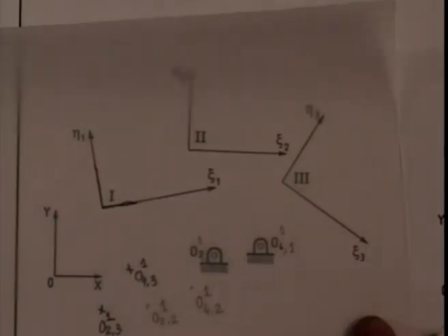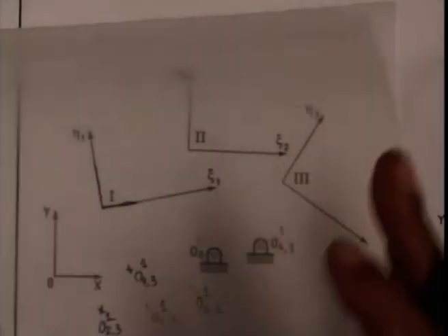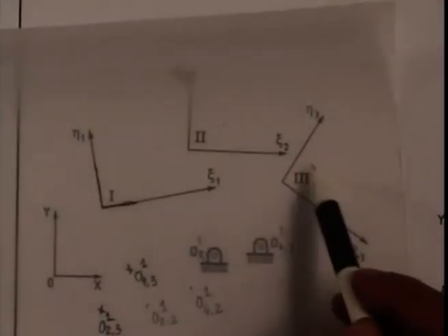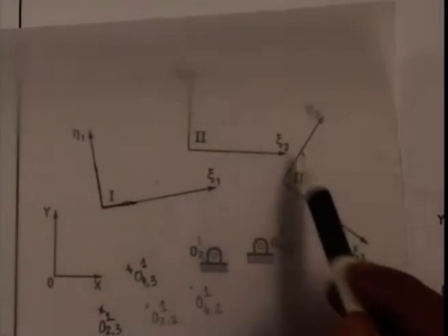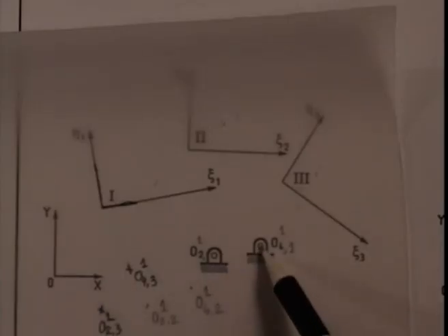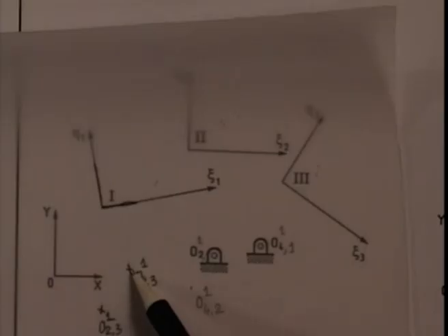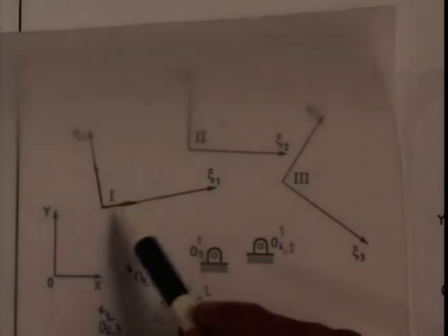So if we fix the coupler and allow the fixed link to move, the same relative configurations as given by the moving coupler with respect to the fixed link, then the fixed link moves such that O2 goes from O211 to O221 to O231. Similarly, O4 goes from O411 to O421 and O431 by holding the coupler fixed.